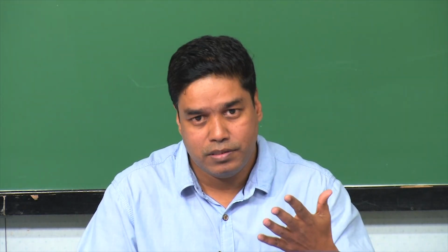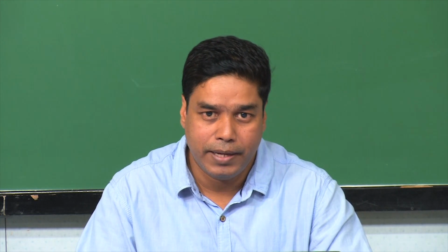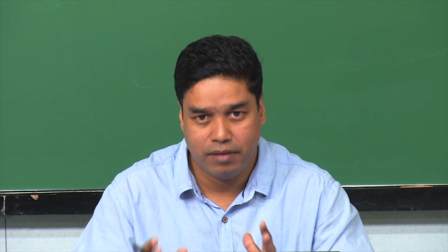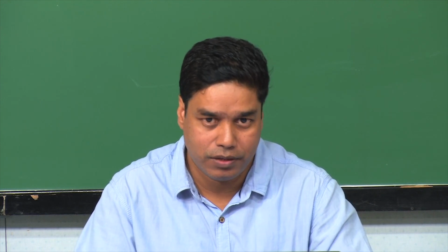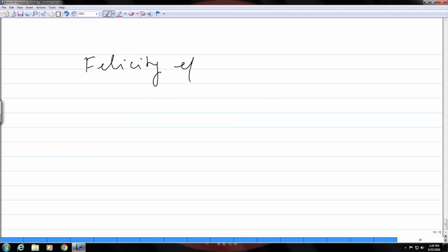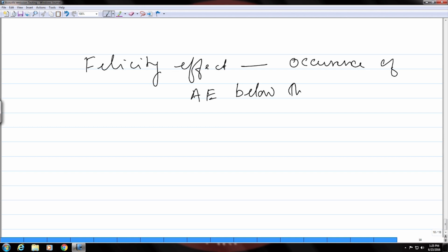No damage is being stated by the Kaiser effect, and when the structure is damaged and you have a big source of acoustic emission, then that is being described by the Felicity effect. Okay. So, as I said, this is about the occurrence of acoustic emission below the previous maximum load.